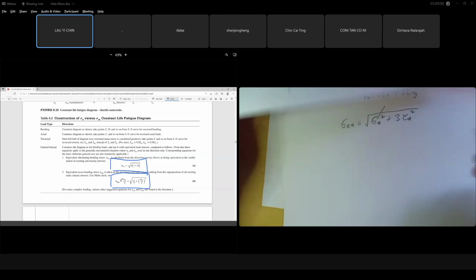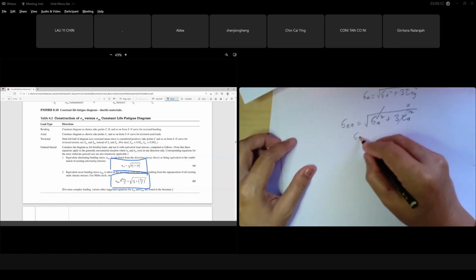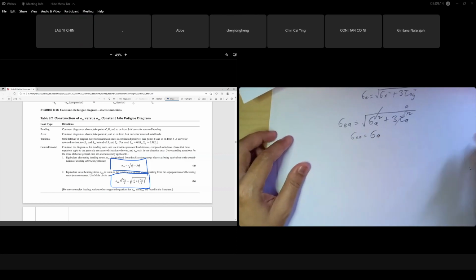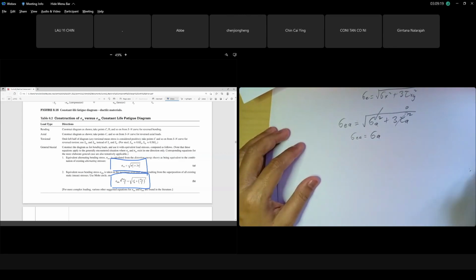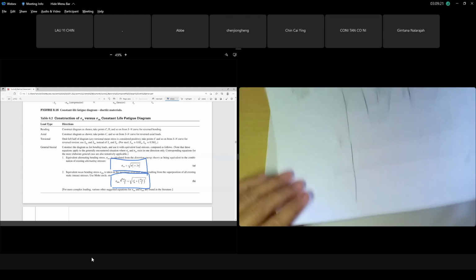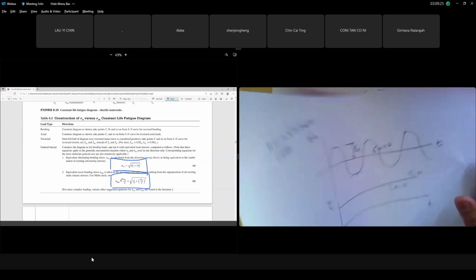No, zero. So this one become zero. Tapi you use the equation, this one become zero. So you punya sigma EA equal to sigma amplitude. Betul tak? Your sigma lah. Your sigma 32 moment pi d cube lah. Okay, sigma amplitude, because sigma amplitude for complete reverse is the value of your sigma max. Kan? Okay, is sigma amplitude.